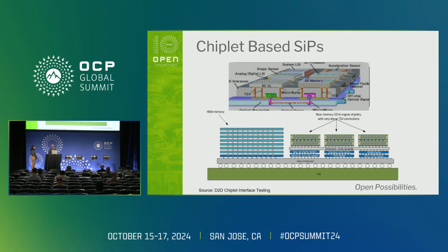And you can see how increasingly difficult it is from this picture, especially showing these micro balls, micro bumps, which are very small in size and pitch, compared to the bumps that actually can be accessed in wafer level testing. In addition, sometimes you need to add sacrificial pads, because that increases the controllability.